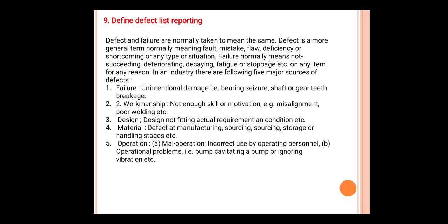Third, design not fitting actual requirement and condition, etc. Fourth, material, defect at manufacturing, sourcing, storage or any handling stages. Fifth, operation, mal-operation, that is incorrect use by the operating person. Operational problems, that is cavitating a pump or ignoring vibrations. These all types of mistakes are considered as list reporting of the defect. Okay. Next question,